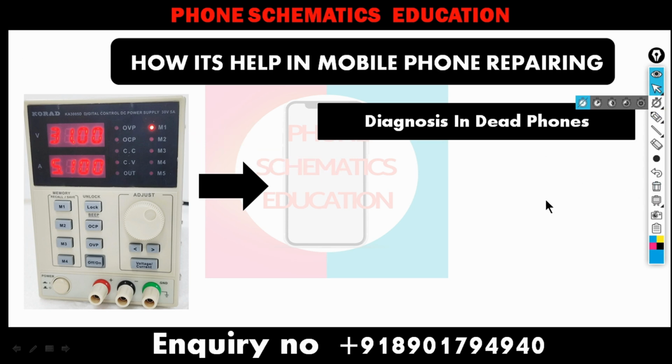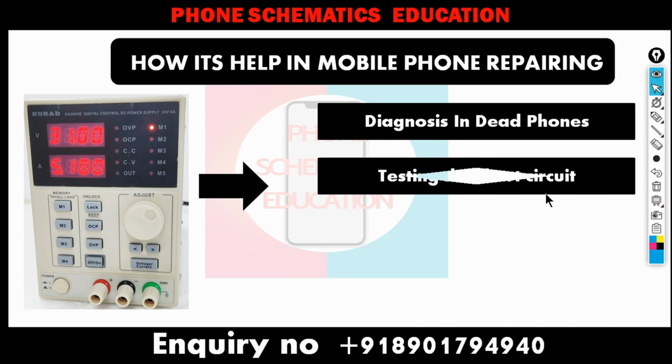Now after this, our next point, testing the short circuit. A DC power supply can identify a short circuit in a mobile phone, I mean the motherboard, right? By observing the current consumption. For example, if there is a higher current draw without pressing the power on off button.